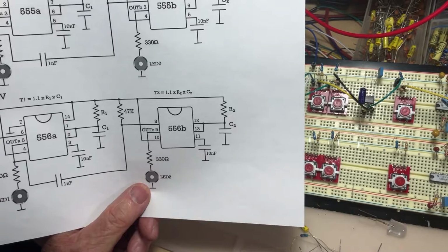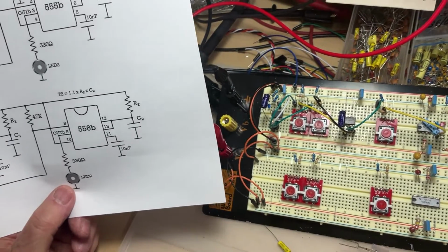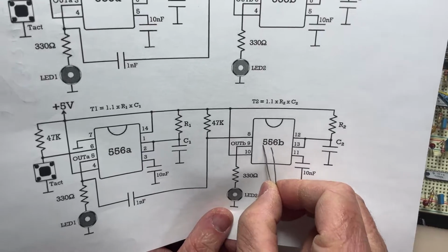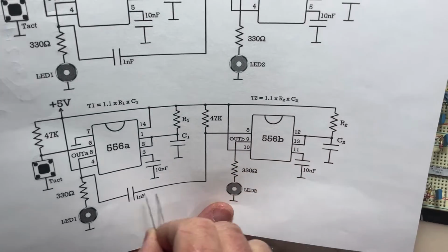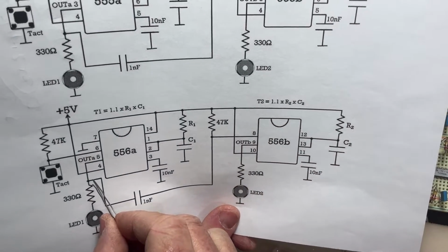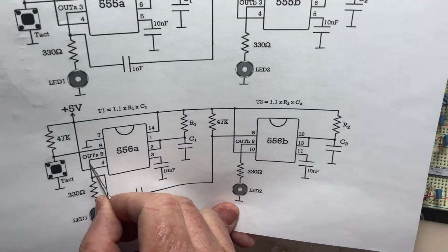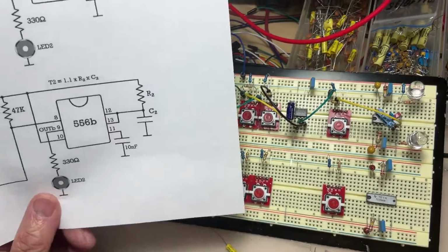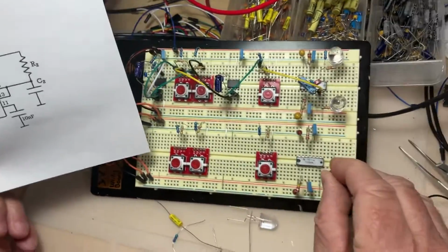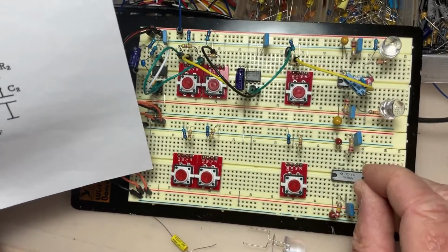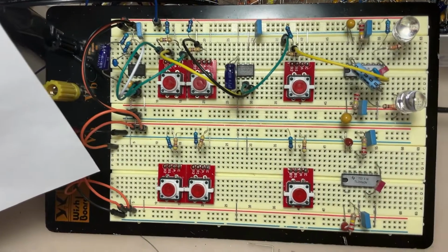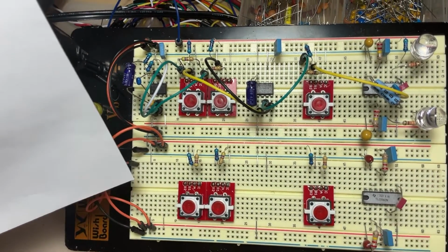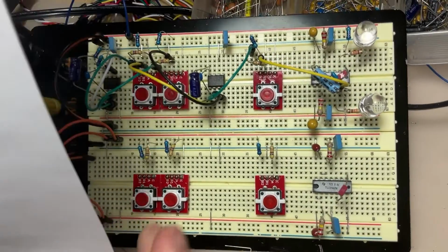Now, what also has to go is the triggering for the second package. It goes between the pin 8 and the pin 5, because the pin 5 is the output of the first, so you have to trigger the next one. Because of that, between the pins 5 to 8, you are going to connect this capacitor of 1 nano, just like that.